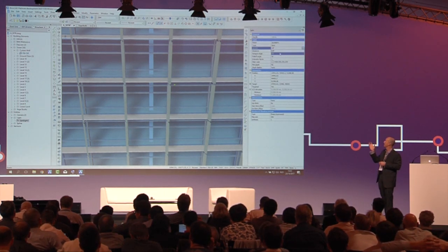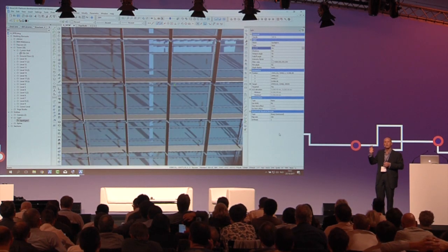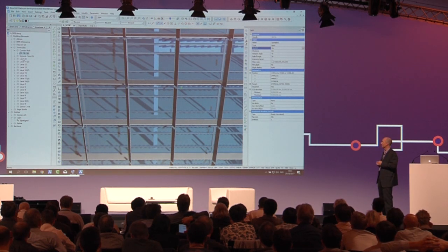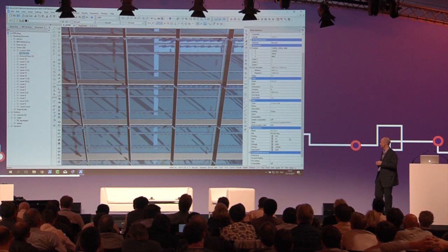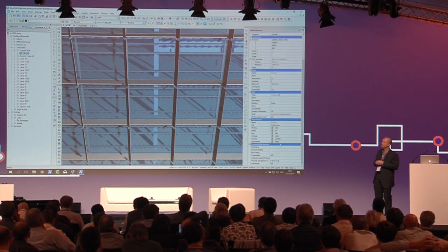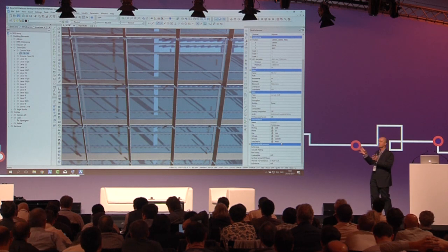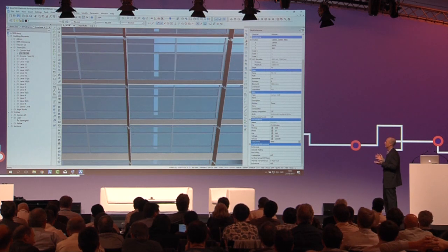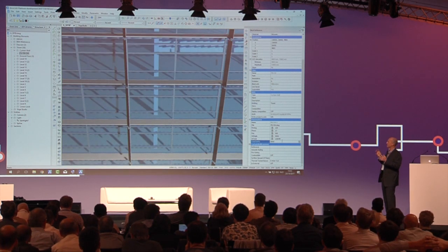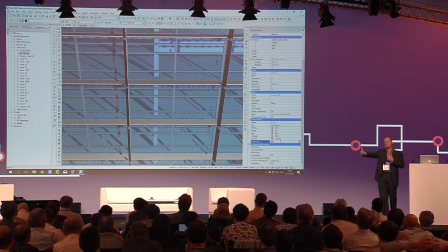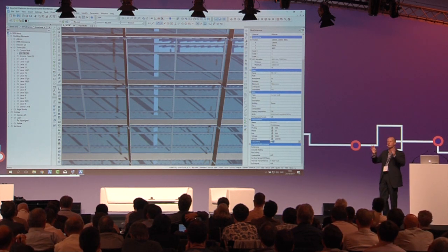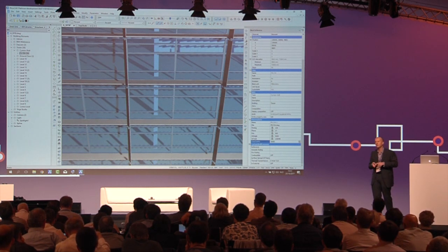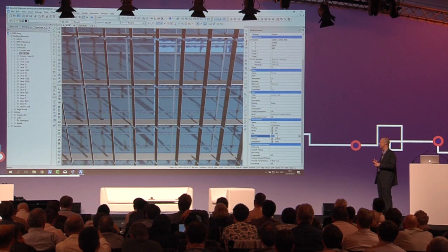So we'll turn on the solar shading, and we'll add some light intensity so that we can see the shadows better as we start to investigate this module a bit more. We could start by changing the fins, which right now are at 4 meters. If we increase the size of those to, say, 8, that doesn't appear like it's going to really work. We'd have to make the fins either really large or tilt the angle, and you wouldn't be able to see out anyway. So let's adjust the fin spacing to 2 meters, and we can also adjust the window spacing to 2 meters.